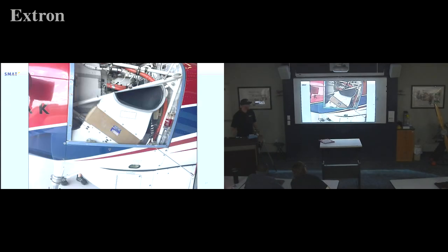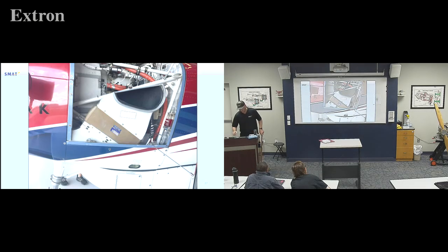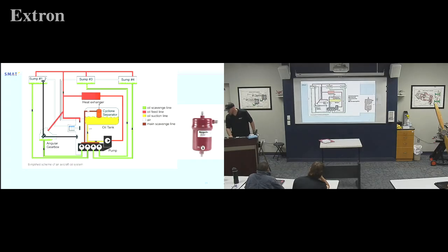And I thought this was kind of fun. We've got our air-cooled oil cooler. So air comes in here when you're flying really fast, goes through the oil cooler, and then out the side of the aircraft. So that's kind of the main place we're cooling our oil. How else do we cool our oil on a turbine engine a lot of times? Fuel, yup. This one has, I might have said that backwards. I think that one's got a door to open and close, so we can control how much we cool our oil, but now I'm second guessing myself. We'll see if it shows up in a later one.